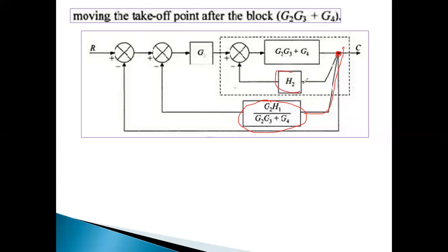So first step, we can eliminate negative feedback. So we can eliminate this feedback into a single block. Next, G1 and this entire thing are in cascade connection. We can match these two blocks. Again, for that entire thing, G2H2 by G2H2 plus G3 becomes feedback. So this becomes H and this entire thing becomes G, G by 1 plus GH again. Okay.